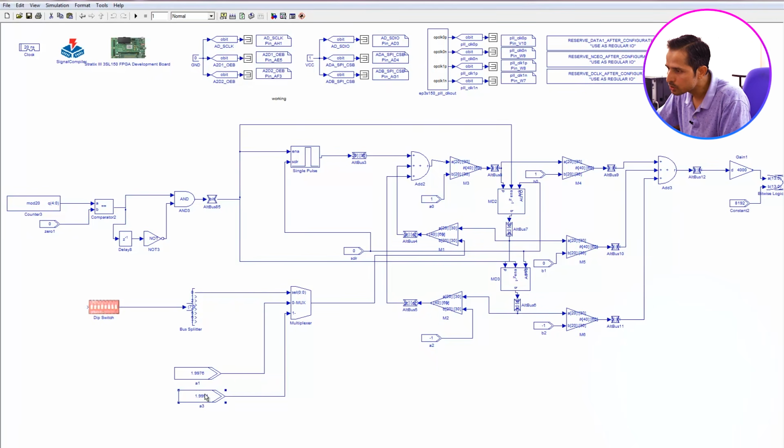So this corresponds to the 11.7 kilohertz signal, which is given to mux input 1, and this is the 20 kilohertz, specifically 19.53 kilohertz, which is given to 0. So the overall program, if we can see, by using the DIP switch, now I will be controlling the oscillator output.